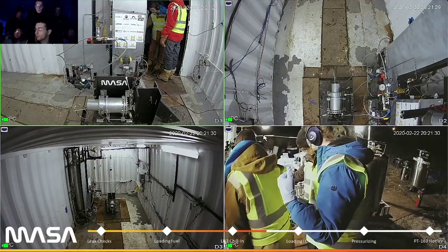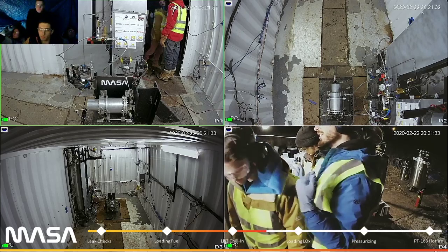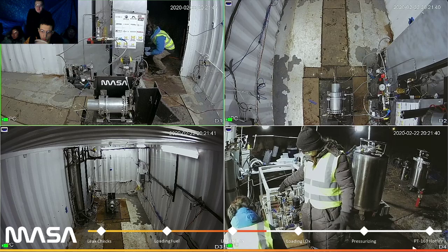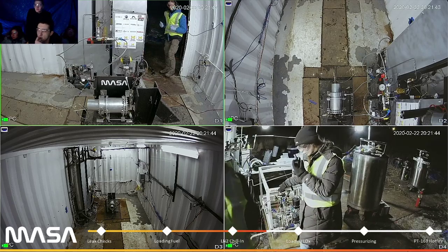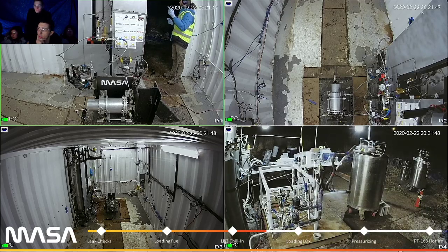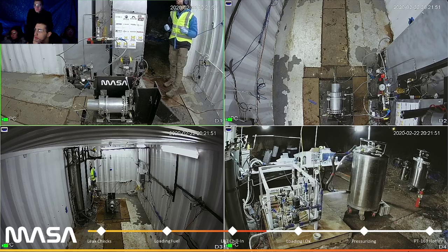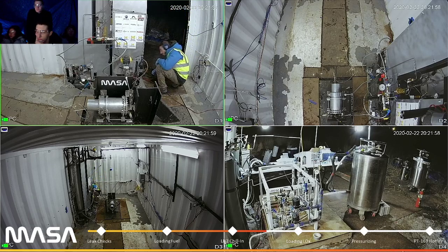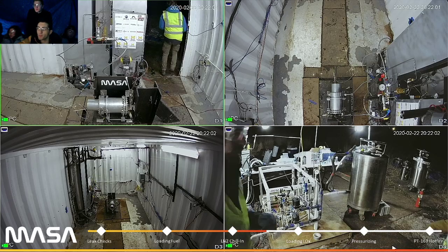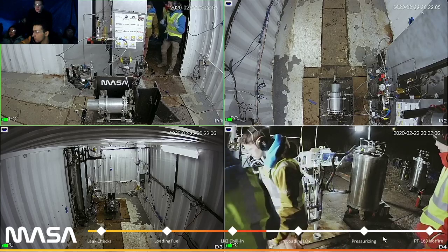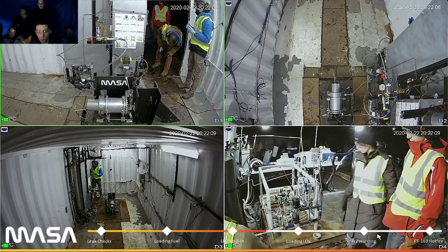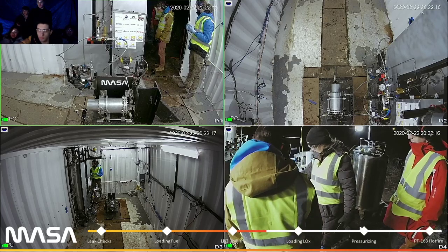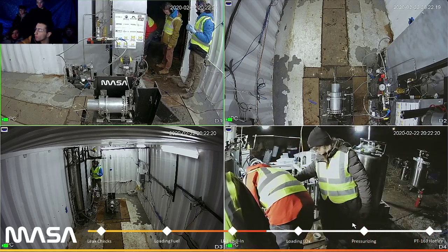I guess it has its benefits, but I wouldn't say high test peroxide makes it any easier. And having a turbine that generates power on a shaft to pump your fluid, I think that is significantly more complex. Having high velocity spinning components in your assembly, I'd say that's a lot more difficult than just simply pressurizing your tanks with external fluid. And high test peroxide is actually pretty hazardous. If you have thermal runaway in a tank of high test peroxide, you can have that explode, like full on explode. Whereas liquid oxygen is pretty stable in its liquid form in a dewar.